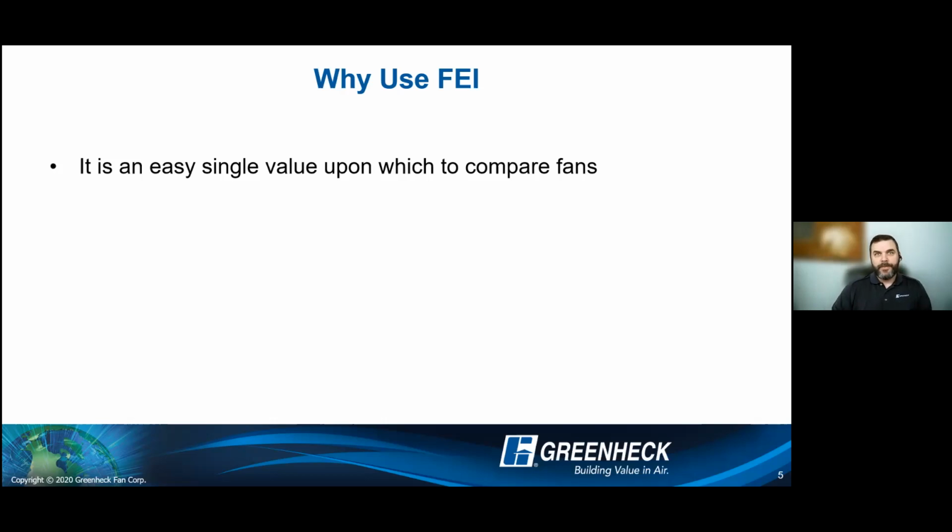And of course, FEI is not going to take into account your environment, as far as like if you're dealing with a smoke control type application, or if you're dealing with an explosion requirement for an application, you have to select the correct fans for those applications. And I'm kind of not going there. You do need to select the right fan for the application you have. But when you compare fans, the FEI is a great way to just rank and order them.